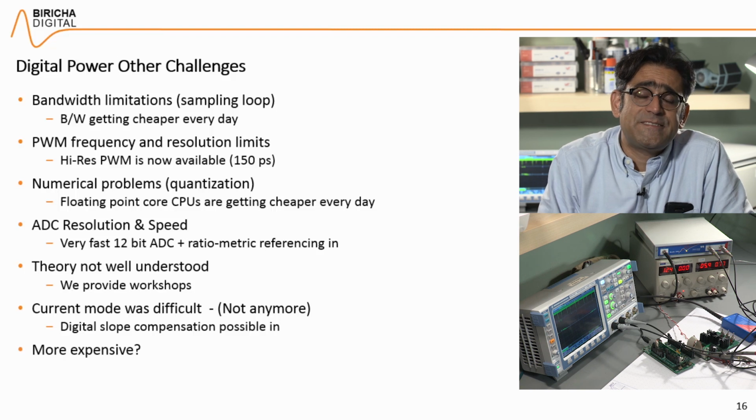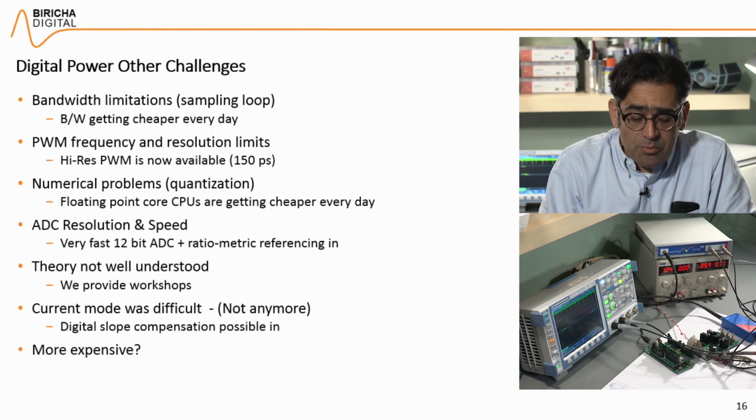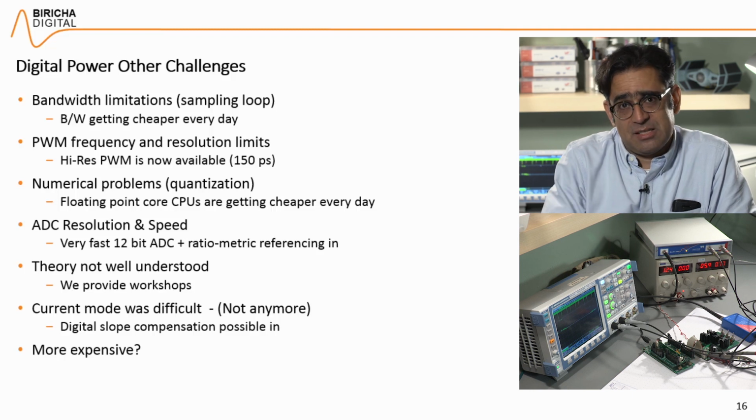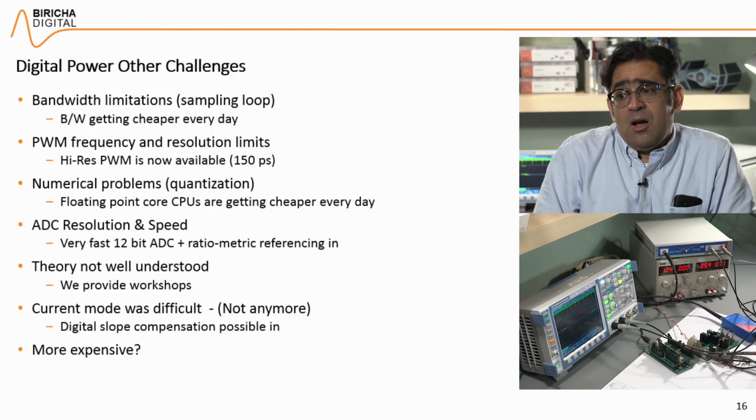Is it more expensive? I don't know. This is something that you, as the design engineer, will have to decide. If you're designing one flyback power supply that takes 230 volts, gives you 12 volts, and that is all it's going to do, then no, analog is possibly cheaper. Cheaper, faster, quicker. If you're doing something sophisticated, if you need several rails, you need intelligence, you need to change the control loop performance, maybe the input line range is too big, maybe the output voltage needs to vary, maybe you need to meet some stringent EMC standard or efficiency standard.